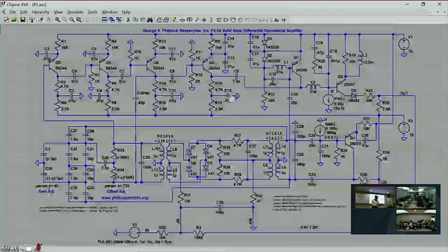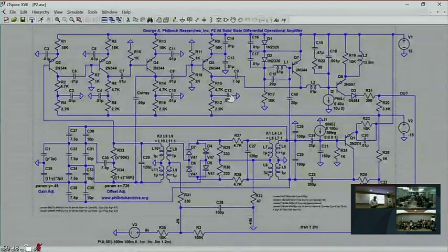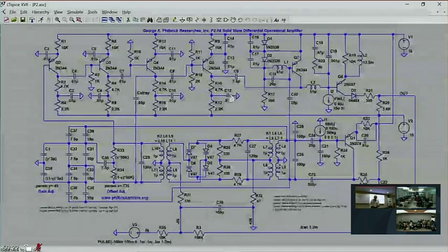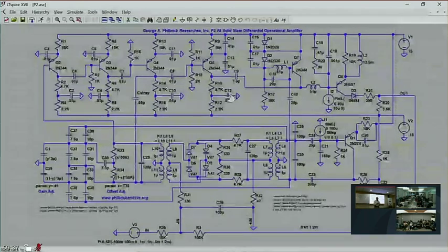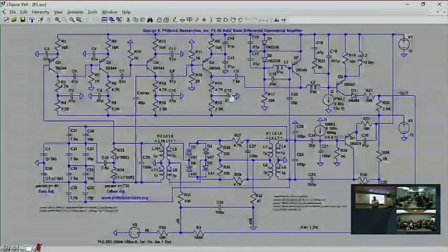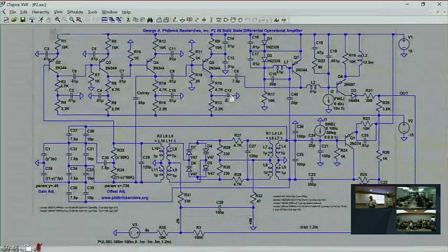But anyway, with this thing here, this thing's more accurate than a slide rule, and you can integrate differential equations. What you do with this is you make the electrical analog to your system, like, and I'll show you how to transcribe, you know, mechanical stuff to electrical component values. And then you optimize the component values so the circuit works right, the analogous circuit works right.